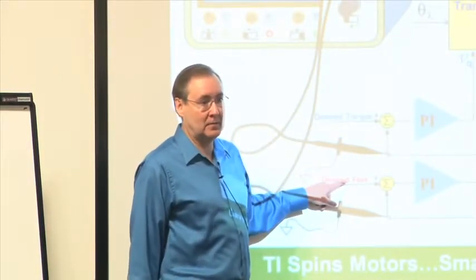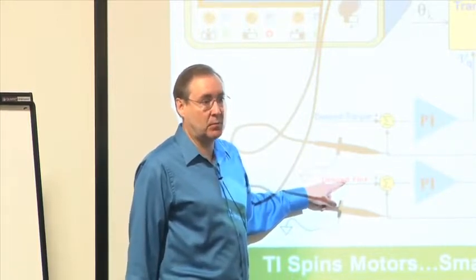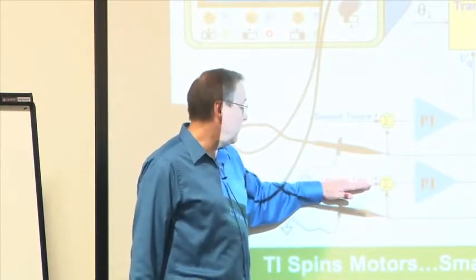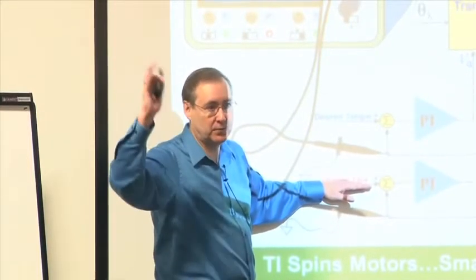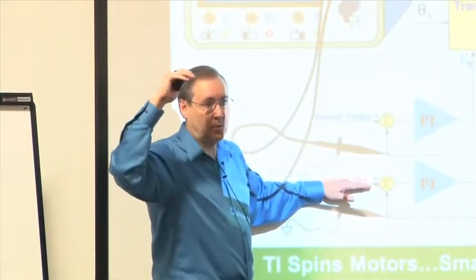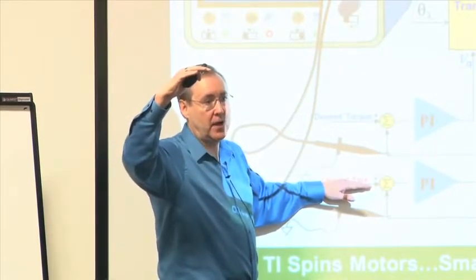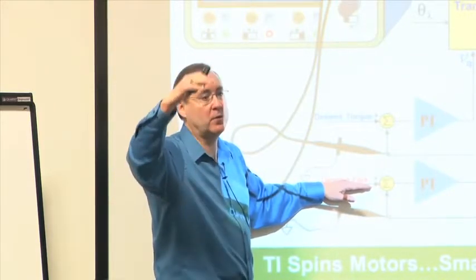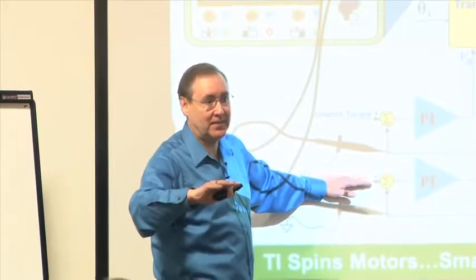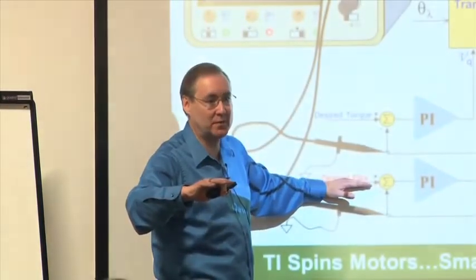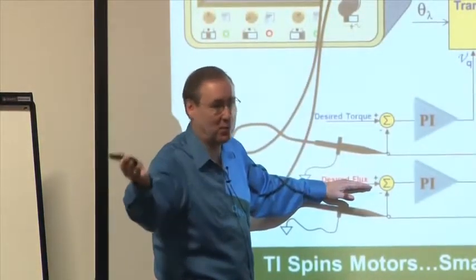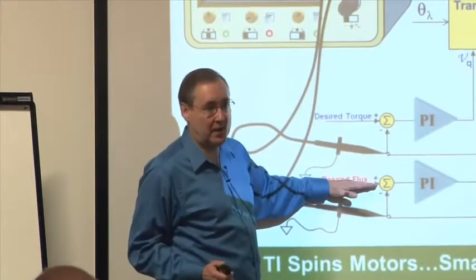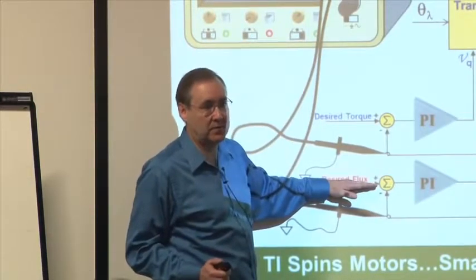When you slip in your motor, yes. Well, actually, the motor will have a rated flux. It'll say, okay, it wants to work at this flux if it's 60 hertz or 50 hertz or whatever it is. For the voltage that it's rated at, you can say, okay, this is volts per hertz. It's like 430 volts at 60 hertz. That's rated flux. That's another dimension for flux, volts per hertz, if you go through and work it out. So I know what that will be then, and I can set that motor to work at that rated flux.